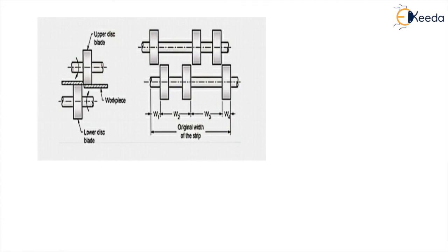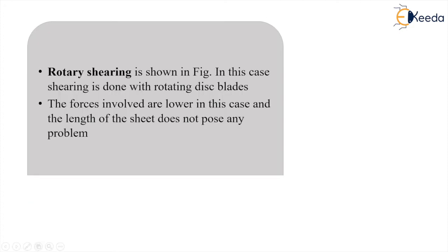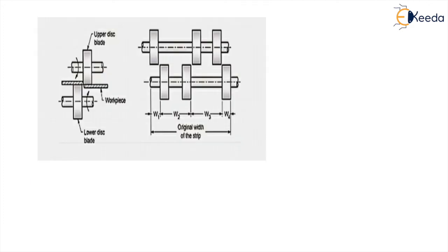And the important thing is that the forces involved in rotary shearing are lower than in square shearing, and the length of the sheet does not pose any problem. However long the sheet is, there is no issue. We are having a very good cutting or shearing operation, with lesser force than square shearing. Thank you.